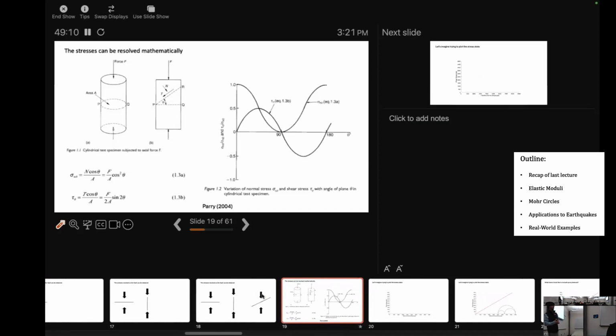Why does that matter? Why is the ratio important? Because if you think about a fault, if you have a whole ton of normal stress and a lot of shear stress, if the normal stress is too high, that fault's not going to move because it's just clamped together too much. If you relax the normal stress, even if you reduce the shear stress, you can get failure. So it's about the ratio. Oh, okay. Thanks. Yeah, absolutely. I think we can adjourn here. Thank you.